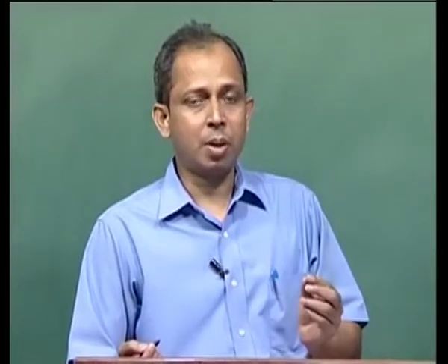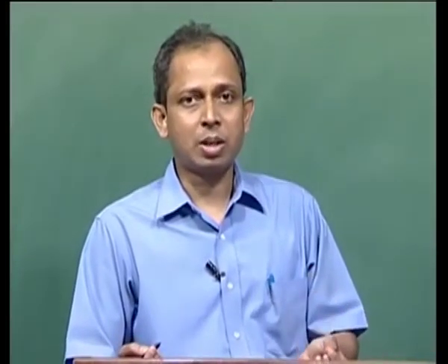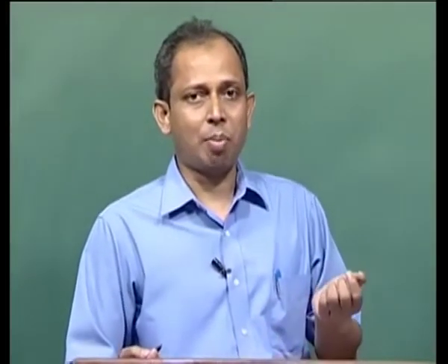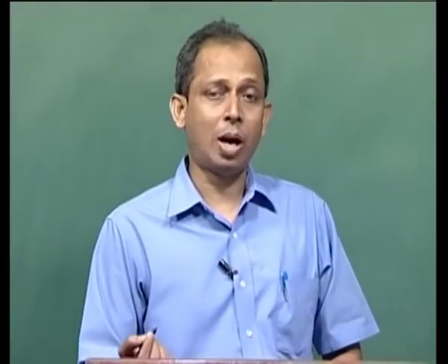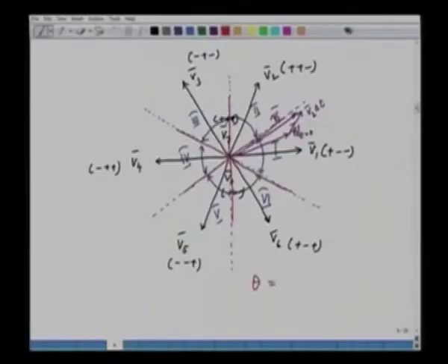So we obtain the flux status and the torque status from the flux comparator and the torque comparator, and then we also find out the information about the sector, in which sector the flux is remaining. How do we find out that information? That information of theta can be found out by taking the tan inverse of psi qs by psi ds.